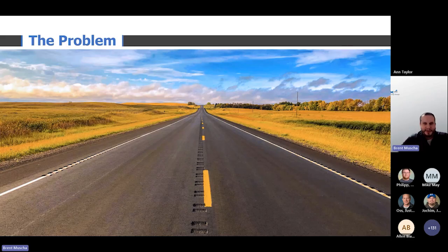Somebody else came and picked up the lath. How are you going to figure out what station or where the station is that you need to mark your full depth core? If you maybe don't have survey equipment, you're stuck with, maybe if you find an approach that you know what station it's supposed to be on, you wheel off from there, or maybe use your DMI and hope that it's calibrated. How accurate are you really going to be with all of that?